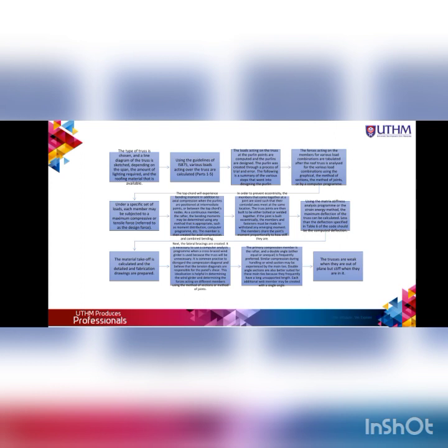Using a matrix stiffness analysis program or the strain energy method, the maximum deflection of the truss can be calculated and compared to be less than the deflection specified in table C of the code. And then the material take-off is calculated and the detail and fabrication drawings are prepared. Next, lateral bracing is provided; it is necessary to use a computer analysis program when cross-braced wind girders are used by the truss.